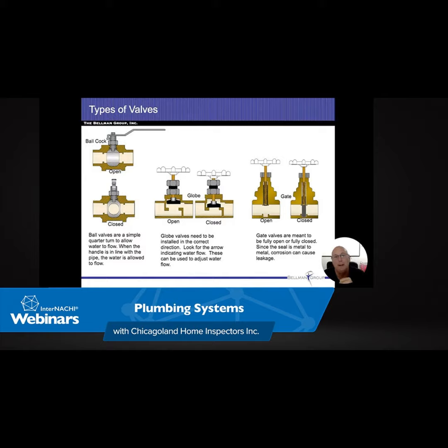But for the most part, we're going to be dealing with vent stacks. That means no solids are expected to flow through that pipe. No water is expected to flow through that pipe. Only air. And typically that's to let air into the system so that we would prevent a siphon from occurring on our waste lines and also on our soil lines.